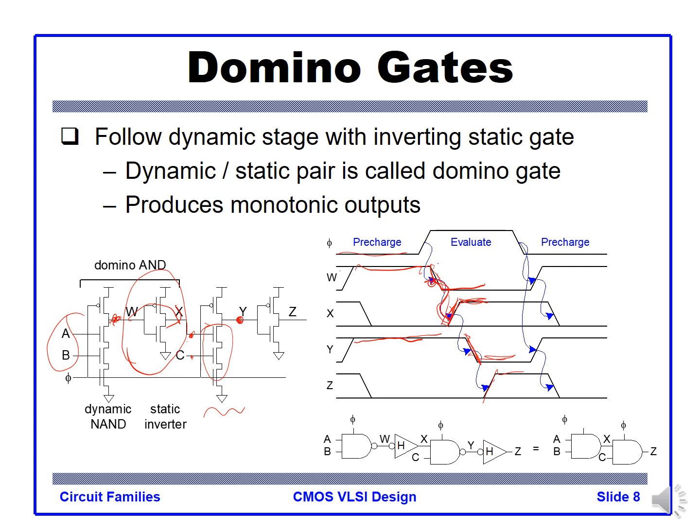So all the events here ripple through the domino, following the change of A and B and the condition on A and B, by adding just a simple inverter. So by adding just a simple inverter between the dominos, we prevent such wrong operation. This guarantees the monotonic output transition.